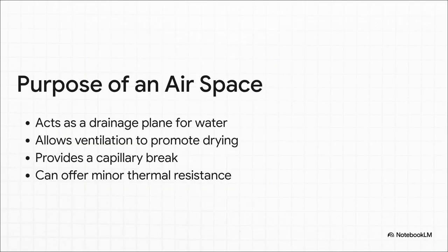And this slide just perfectly illustrates its main job, managing water. So when that hard, wind-driven rain gets past your siding, this space acts like a drainage channel. Gravity just pulls the water down and out. It also lets air circulate, which is huge for drying out any leftover moisture. This is the heart of a rain screen system, a huge topic for the PDD exam.